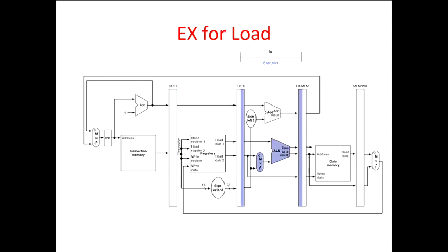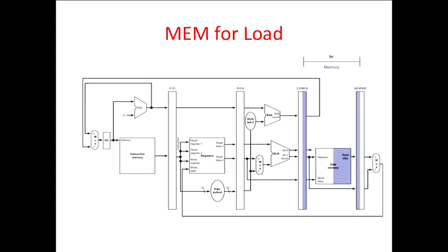Then the third cycle of execution, there's one instruction. Now we get to do the actual ALU operation and capture the result in this register at the end of that pipe stage. In the fourth cycle, we actually do the memory access. So now this instruction's moved down the pipeline. It's got to the memory access stage. We read the memory and capture the result.